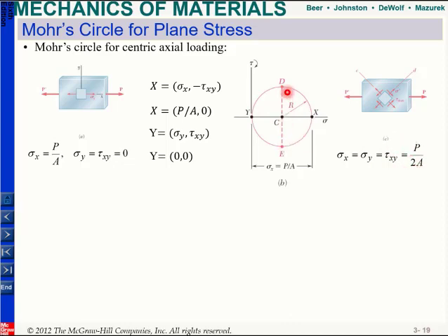If you are on this plane, make sure that I have my shear stress, but I still also have my normal stress. My normal stress will be equal to my average stress. So the point D, if you write the coordinates, is sigma average and minus shear maximum. And this point is also my average and this time plus shear maximum. So my XY system is already my principal stresses, and you can also guess it because your shear is 0. On the principal axis your shear is 0. And if you want to find your maximum shear stresses, I need to rotate it 45 degrees.